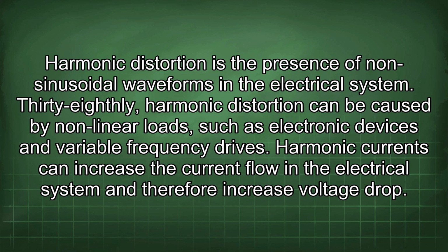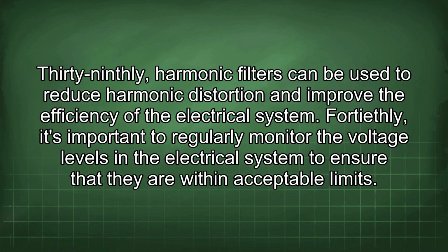38thly, harmonic distortion can be caused by nonlinear loads, such as electronic devices and variable frequency drives. Harmonic currents can increase the current flow in the electrical system and therefore increase voltage drop. 39thly, harmonic filters can be used to reduce harmonic distortion and improve the efficiency of the electrical system.